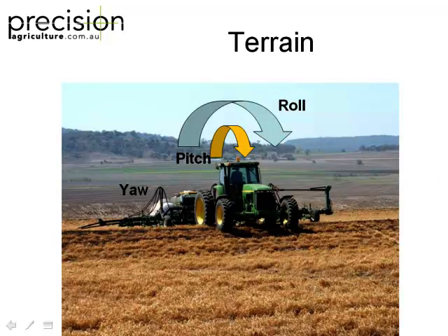Also, these systems need to be terrain compensated. So most of the major brands now all terrain compensate. So when you're going up and over banks or whether you're rocking and rolling, you've got 3 metres of leverage that can make a huge difference on the steering. So they've got terrain compensation built in now. Some of them have got accelerometers, gyros, magnetometers, all sorts of things to really correct for that. But you need to calibrate that, and if you don't calibrate it properly, it drives like a hairy dog.